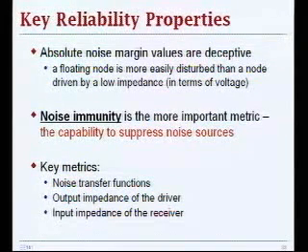So obviously when you have higher impedance of the receiver, that's good because it doesn't provide a lot of loading to your previous gate, and it doesn't affect much your signal levels. It's also very desirable to have low impedance of a driver because that provides really solid voltage levels to the next gate, and also gives sufficient drive capability.